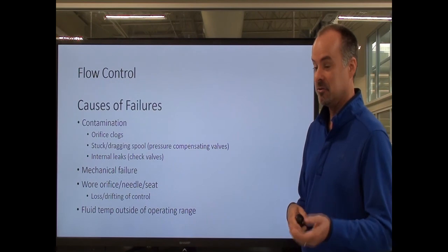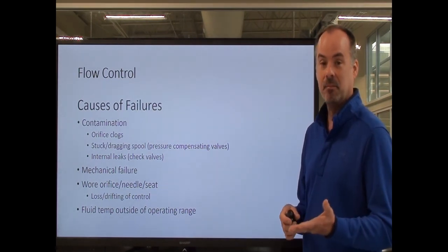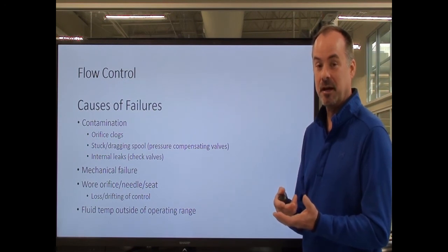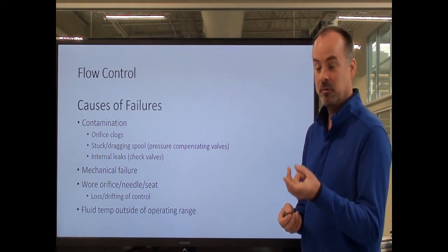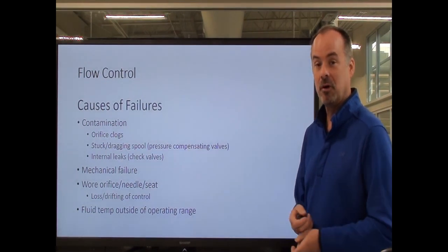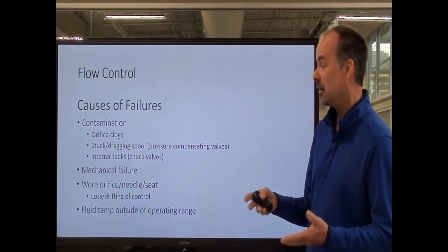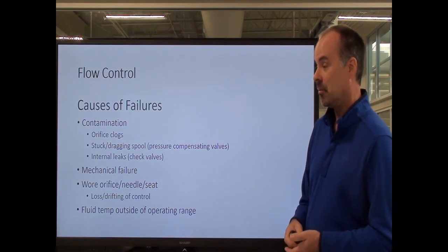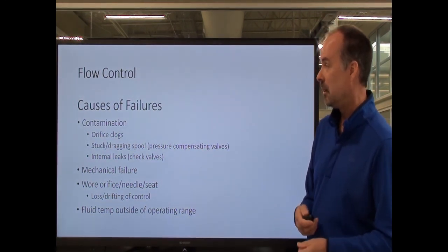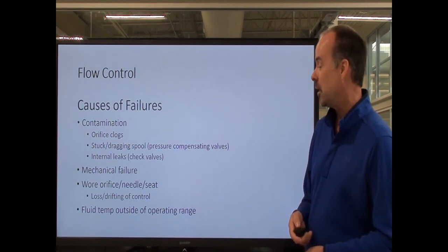And if your heat exchanger clogs up, and I've seen that happen before, where the water's supposed to be flowing through to cool it, much like a radiator, those tubes in there can get clogged up and stop the flow, and then you're not able to cool the hydraulic oil, and it can get too hot, and it can cause you problems of not being able to control the speed and get your speed control out of range.